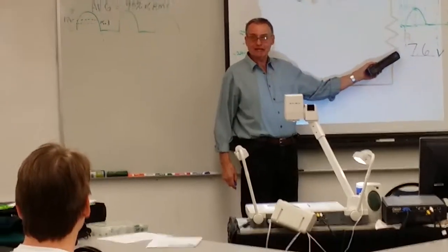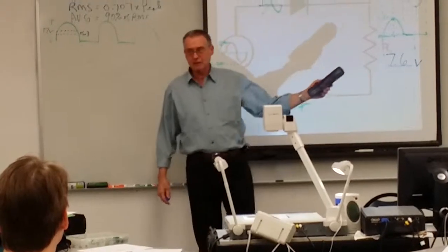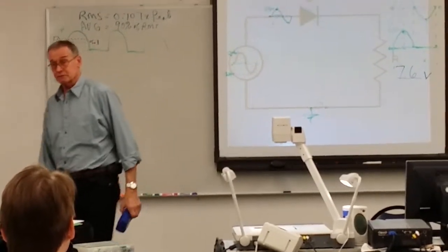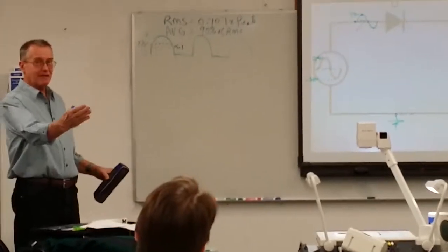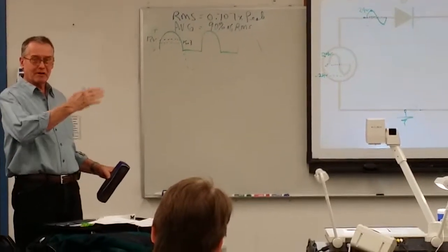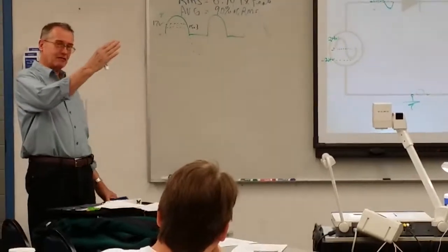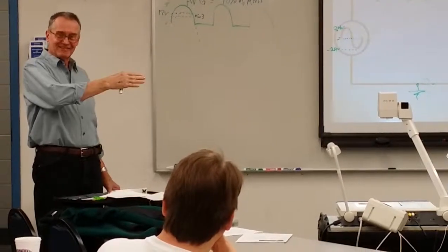So this load is like a potentiometer. It's going from 10 ohms to about 150 ohms. So if it's drawing 10 amps discharge, it'll draw 1 amp charge. That's why when the needle gets all the way over and it says green, you know it's fully charged.